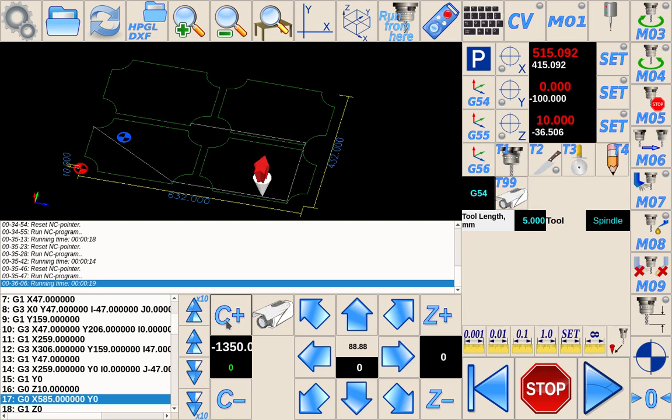If the angle between two lines is more than a given minimal angle, the CNC control automatically adds a lift up, knife rotation according to the next motion direction, and then lift and then move down.